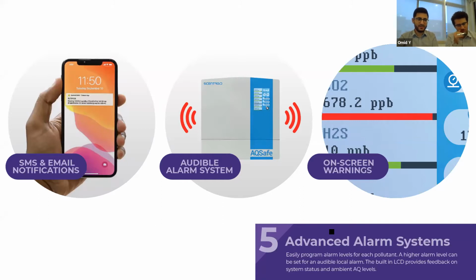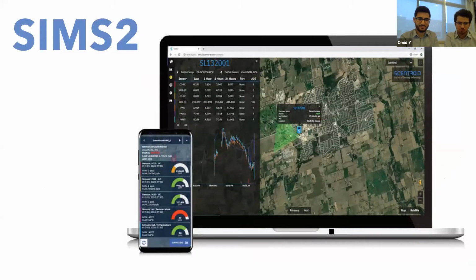On the next level, if you encounter a slightly higher concentration, you'll get an on-screen warning. You can see on the right an example here, CO2 being shown in red, so the screen will show a warning as well. However, if the concentration goes even higher, you can also get an audible alarm. Here in the device, we have an audible alarm that will sound intermittently, telling you that the concentration is now exceeding the 3rd threshold that you set on the device. All of these, of course, are configurable per device and per customer, as per your needs, so you can configure them as you would like.